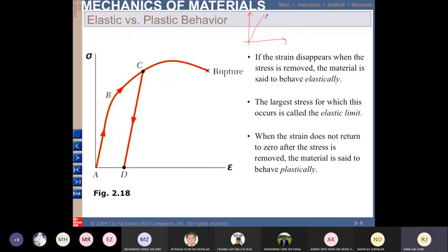But this is the elastic region of the sample. When I say that the brittle material is not elastic, it means it does not have the ability to return to its original dimension once you give force. So once you try to deform them, they will abruptly fail. Do you understand?